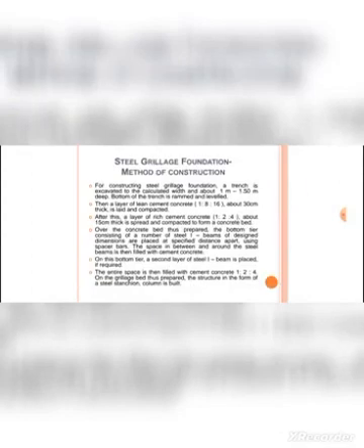Detailing the steel grillage foundation, discussing the method of construction. First, we have to construct a trench with a depth and width of about 1 meter to 1.50 meter, and the bottom is rammed and leveled. A lean cement concrete layer of mix 1:8:16, 30 centimeter thick, should be given and compacted. After that layer, we give a rich cement concrete layer with the proportion of 1:2:4, about 15 centimeter thick, and spread over the concrete bed.